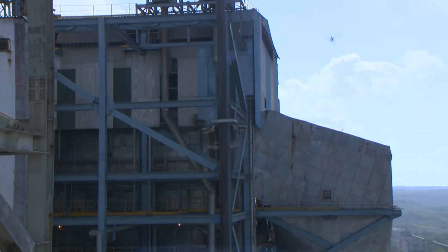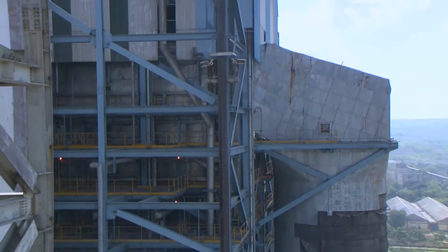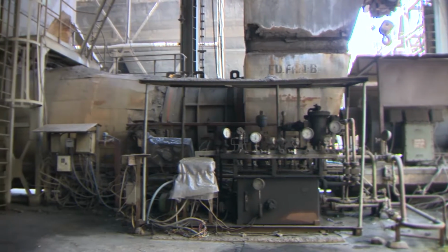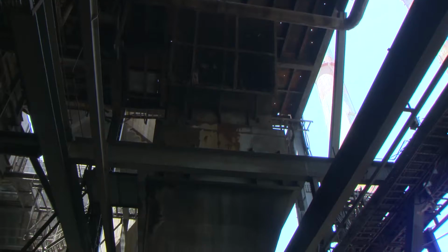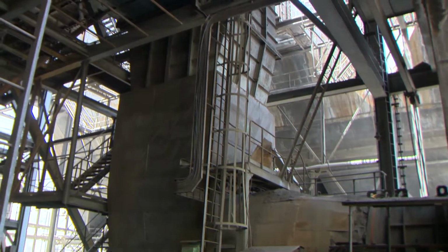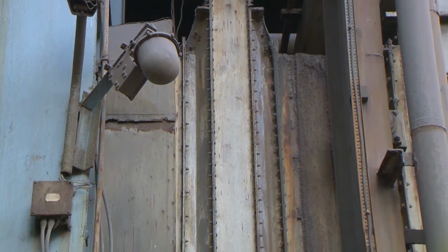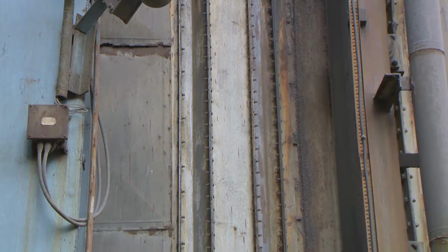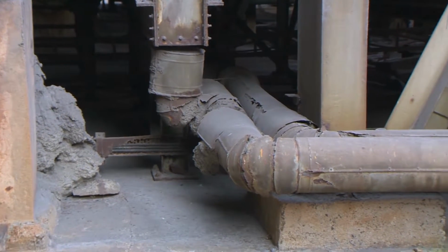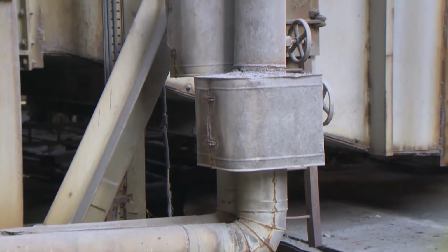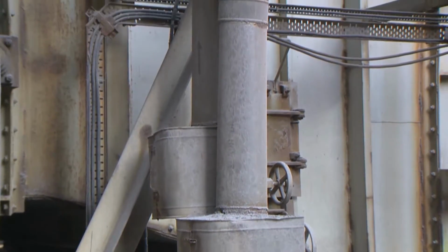Draft system. Balanced draft system is adopted in the boiler. The forced draft fan of axial flow, variable blade pitch control type sucks air from atmosphere and supplies for combustion. The steam coil air preheater is placed at the outlet of FD fan to increase the air temperature during initial light up of boiler. The steam taken from auxiliary steam header will be used for heating the air passing through steam coil air preheater.